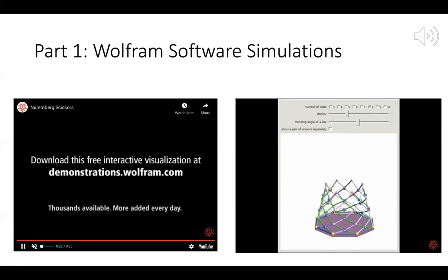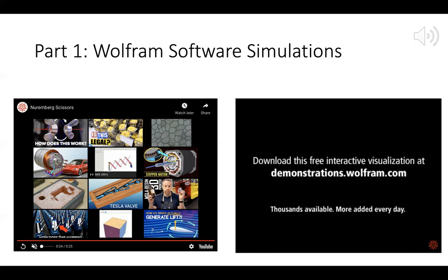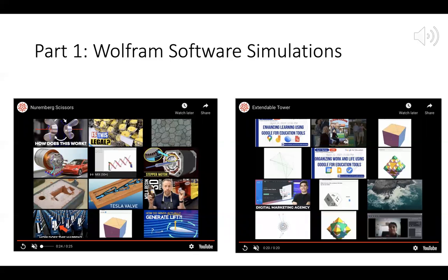And I experimented with these by changing the control variables that go into making the components of all of these structures. Through my simulations, I learned that by using a scissor hinge type, I can create numerous forms of transformable structures, and the visualization helped me get some clarity on how the hinge actually works, and that the least amount of components to a scissor hinge gives more of a lightweight and compressed structure that will be easier to store and transport.